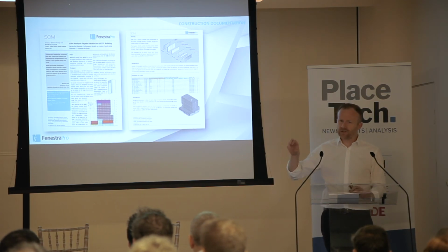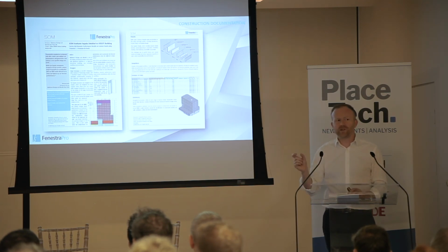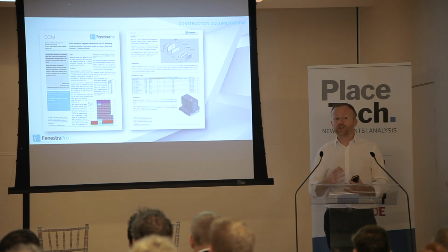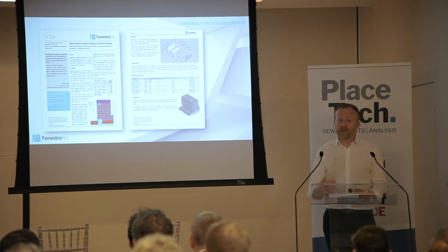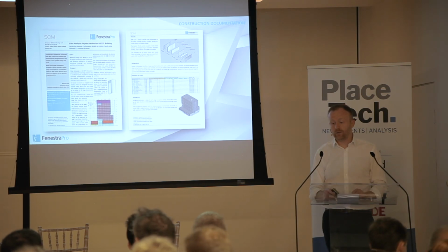But if we know that glass, solid panel, concrete and frame all have different thermal performances, how do we know what that X is when we start changing the ratios between them? Or what happens when I change my frame from 2 inches wide to 2.5 inches wide? So again, FenestraPro gave them a really quick and easy way of defending that 0.25 U value or whatever it was, staying within the typology, using their really detailed model and executing it quite well.